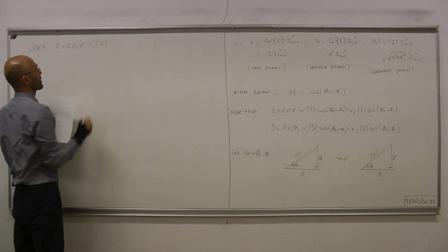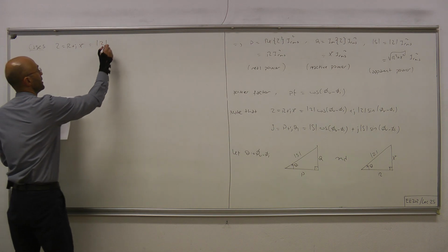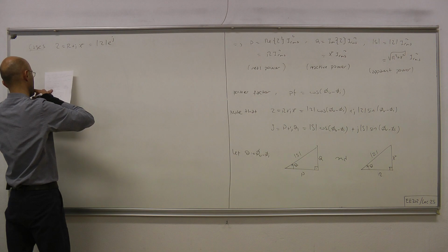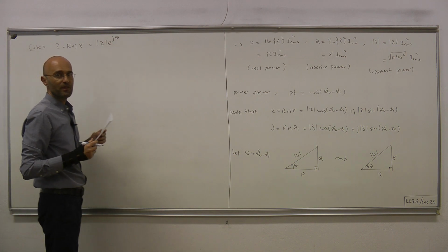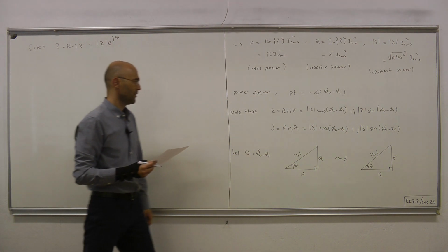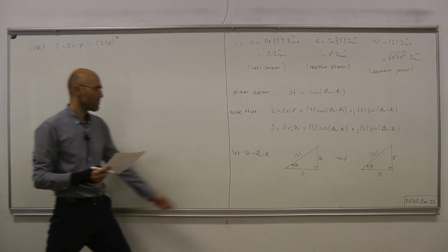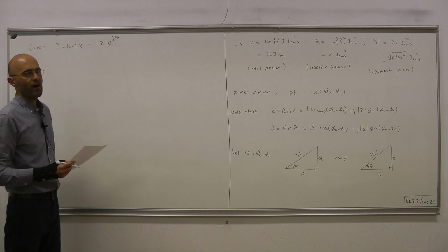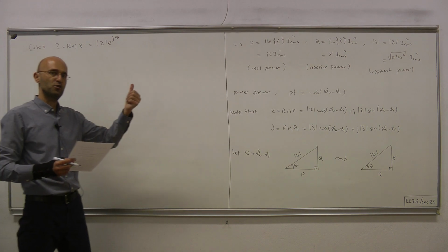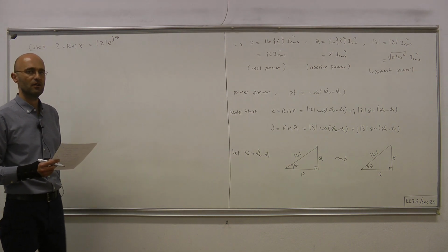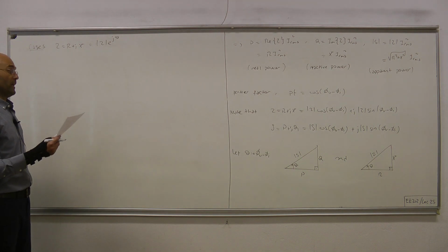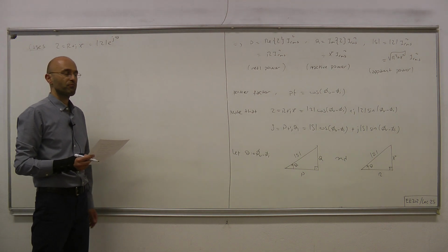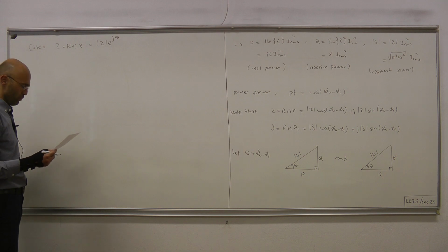Okay, in polar coordinates it's written as e to the j theta, and theta equals the phase difference between phi v and phi I, phi v, phi I being the phases of the voltage and the current at the port terminals for our one port.